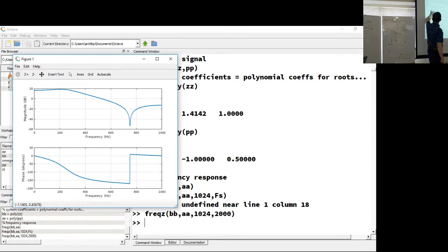Overall gain is something like 18 decibels. So this is not a unity gain system. It has some gain on the filter. It's okay if you need the gain on the filter, but usually a filter is just a filter. It just does the filtering and you have the amplifier somewhere else to do the amplifying. So now we can rescale the system to unity gain.